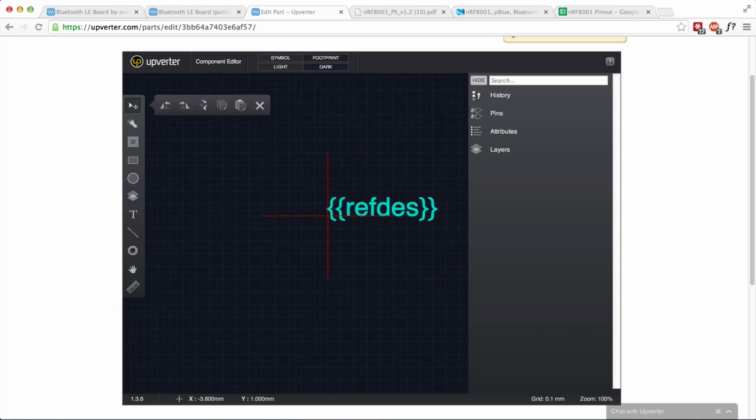It's the same thing. On the left side, you've got all the tools you need to create a footprint. This is the footprint generator, which is what we're going to use, and this is what you'll be using for most of your footprints. This generates a footprint for you automatically. We have a BGA generator, so this generates BGA footprints. And then after that, we've got all the tools that you need to create a footprint manually.